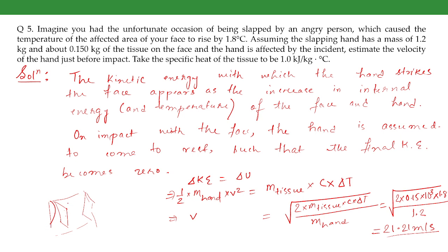If you consider that the mass of the hand is moving at a velocity, then you are moving it, resulting in some work, that is force times some displacement. But in this case it won't be crossing the boundary. Yes, that's why I'm asking. So basically it is not crossing the boundary, it is within the system, and hence it will be considered as internal energy.